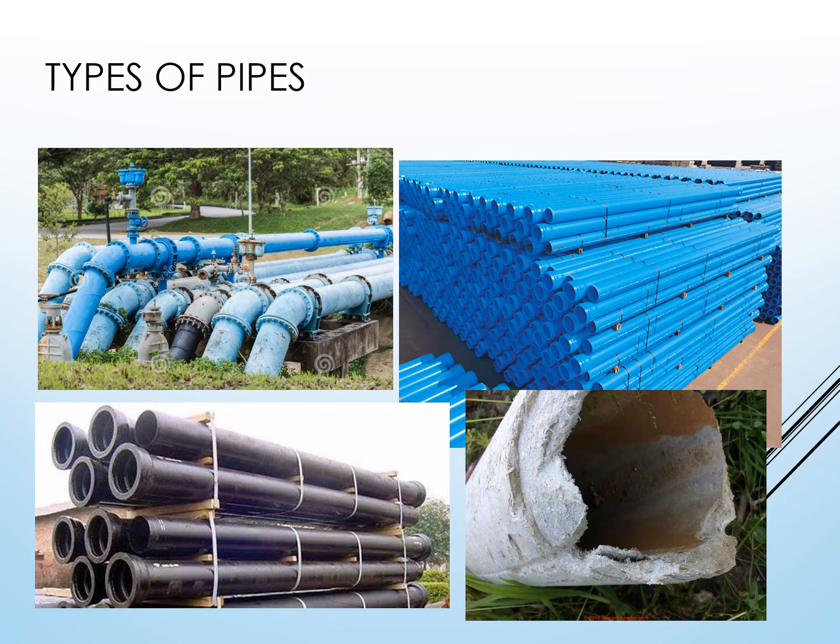Here you've got different types of pipes. Here we can see that we have some steel pipes. A lot of times when you have steel that sits above ground, you're not going to actually coat that in concrete. Right here, you can see there's actually concrete mortar that's been applied to the outside. Anytime you have steel pipes that are underground, having that concrete mortar on them helps to protect them.